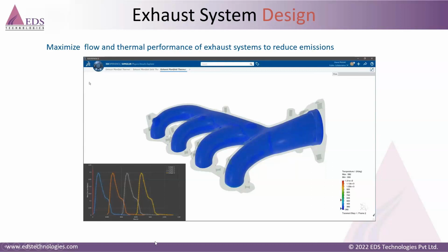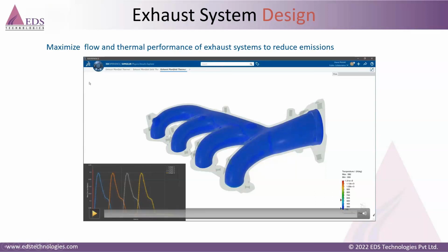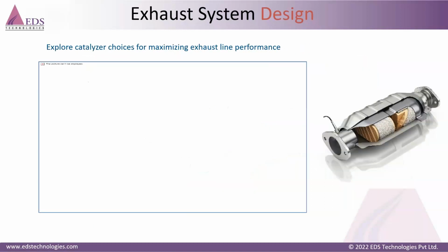Previously I was talking about placement of the components for optimal cooling. We worked with one of our EV customers, where the electric motor was getting heated a lot, and by using the generative design approach, we were able to modify the design as well as place it in such a way that about 30 degrees of temperature reduction was achieved for that particular project.